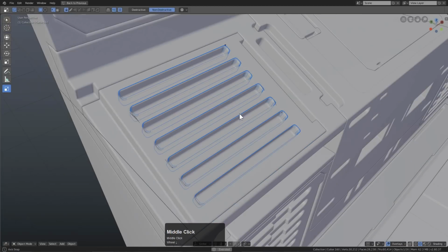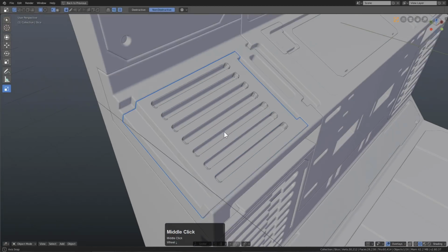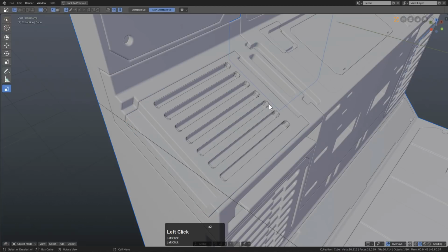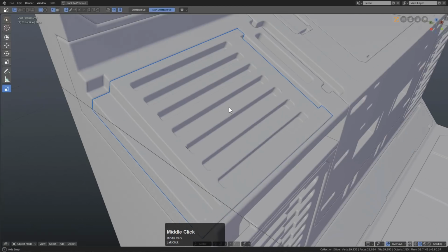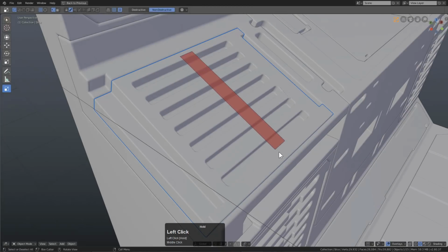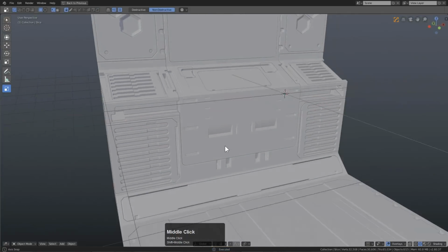So right here, we have a couple of choices. We can either lower the bevel modifier, or actually, there is no or. We fixed it. The other option was just putting a blue box in here. Blue box is basically a tool for cutting in support edges. And support edges help booleans work out, especially if you're cutting in an area that isn't really supported.